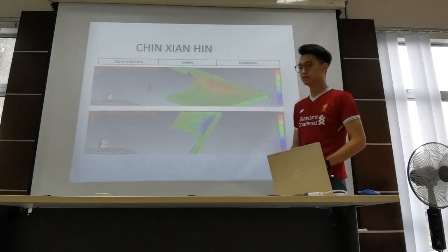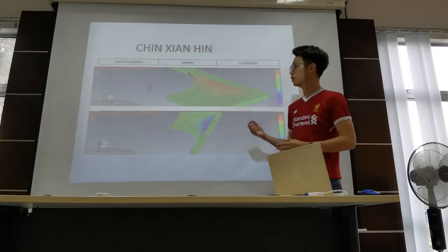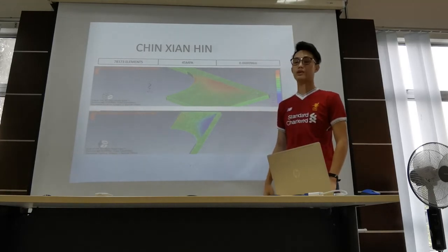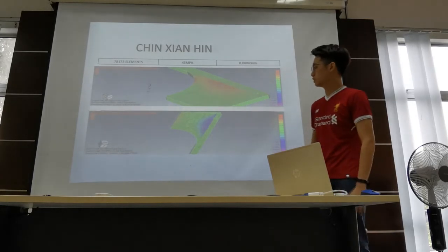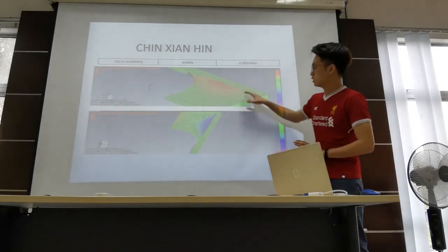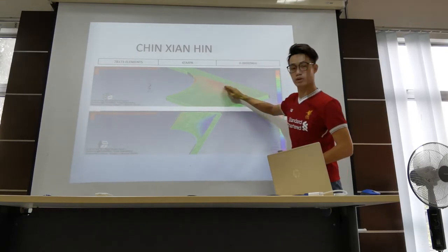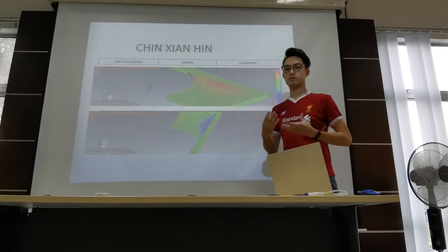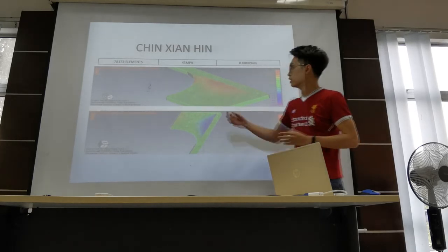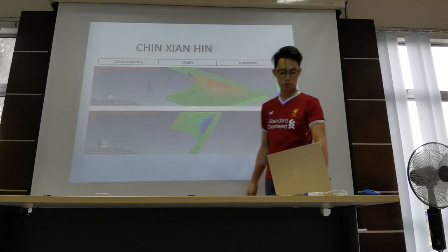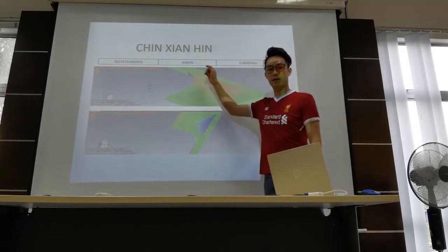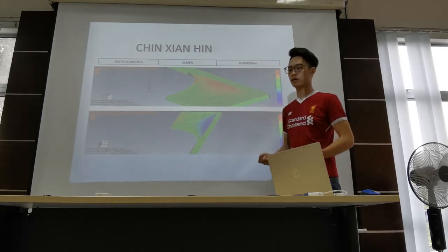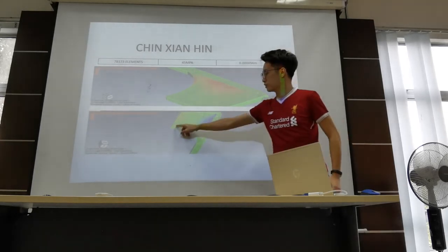And finally, this is my simulation, where I put as many elements as possible, 78,173 elements. Here we could see, as proposed, the table part next to the part where we fix is where we get the most critical stresses. Through my simulation with the most elements, we can see the stress again increased from 41 to 45, and the displacement increased from 5 micron to about 9 micron at the edge of the table.